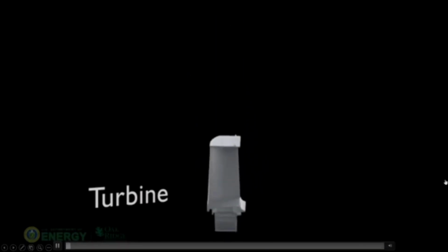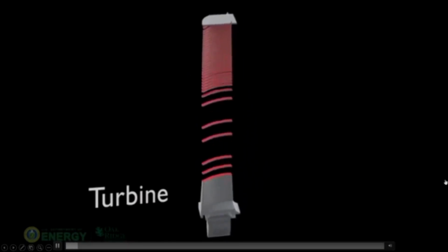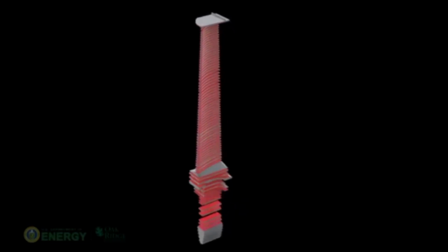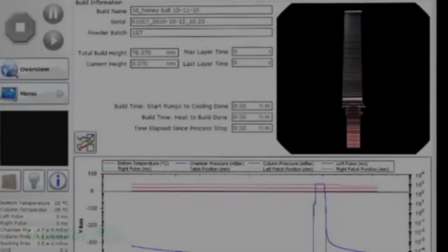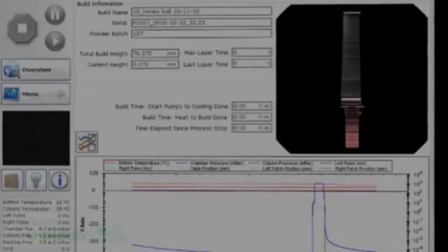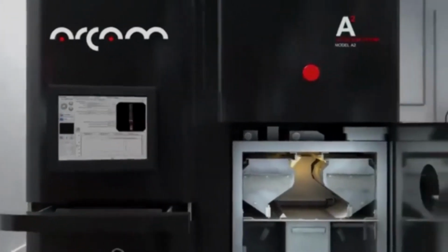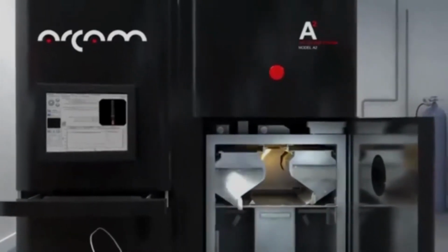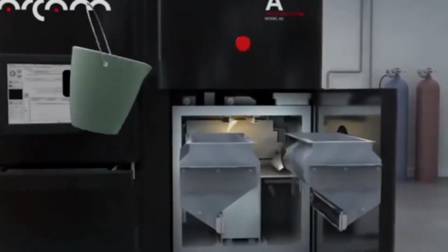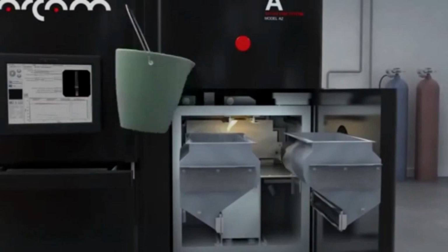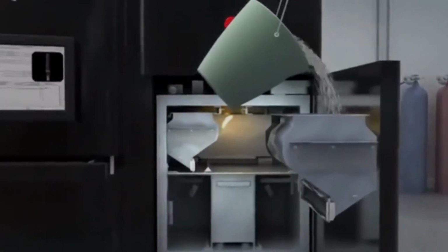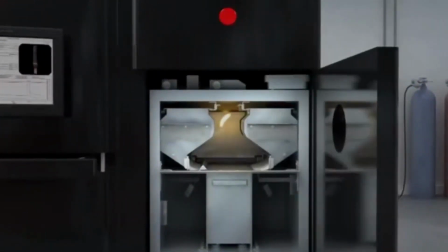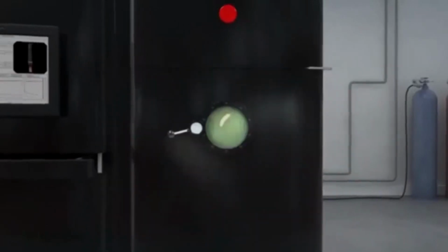So for example, someone wants to build this particular part by EBM. The first step is of course to do the slicing. Slicing can be done by utilizing a CAM package which we have already seen in our CAPP. Then it is appropriately transferred to the machine software where there are two hoppers in the machine in which we first provide the powder particles, and these two hoppers used to be available on top of the build platform.